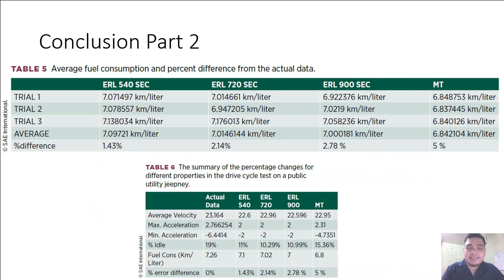Lastly, in the process of using the conservation of energy road load method, the method uses likelihood estimation. In addition to the speed factor considered, acceleration factors and load factors are taken into account, which makes the drive cycle more detailed. The results show that the drive cycles generated using conservation of road load energy criterion are more scientific, reasonable, and drivable, and the development based on it is more representative compared with the microtrip method.